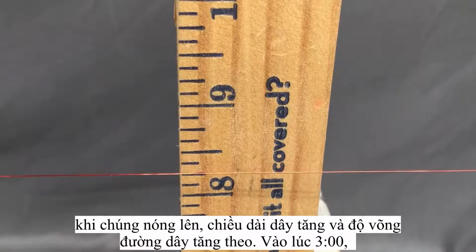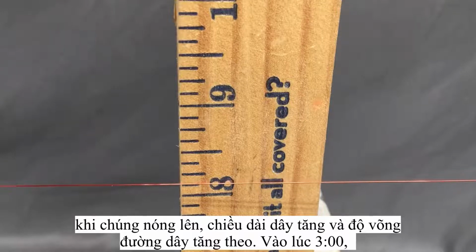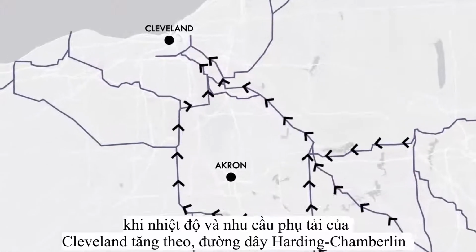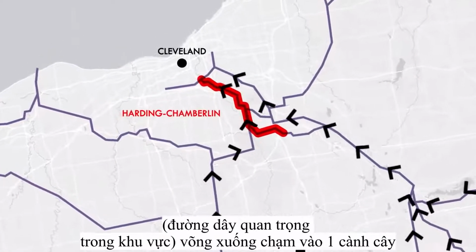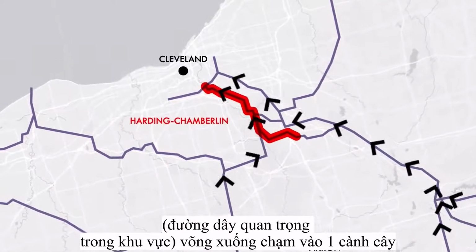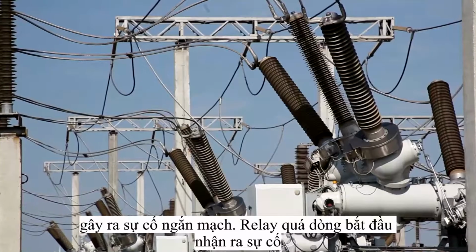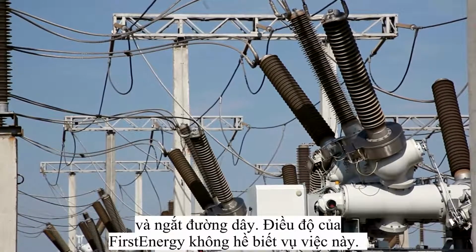As they heat up, they expand in length and sag lower to the ground between each tower. At around 3 o'clock, as the temperatures rose and the power demands of Cleveland did too, the Harding-Chamberlain transmission line, a key asset for importing power to the area, sagged into a tree limb, creating a short circuit. The relays monitoring current on the line recognized the fault immediately and tripped it offline.